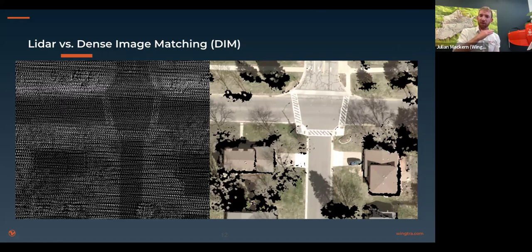It's interesting that after 120 meters, after 400 feet, it's hard to get good data on the side. So actually, the amount of area you can cover over 400 feet doesn't really change that much. It doesn't get better. So 120 meters is the highest that we recommend to get good data, and 90 is even better because you have a better density per square meter.